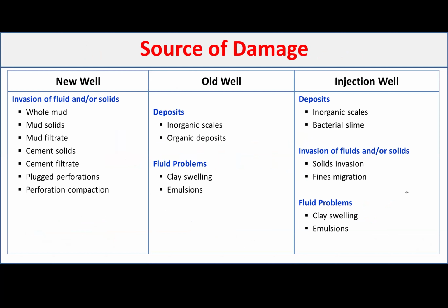Or during the completion, when you are doing the perforation, maybe you have some sort of compaction happening to the perforation, and you have a lot of debris in the perforation that you need to clean up. So if it's a new well, you will always like to review the drilling program and the completion program, and be pretty sure nothing went wrong there. That will be the key to identify what type of damage you are having.